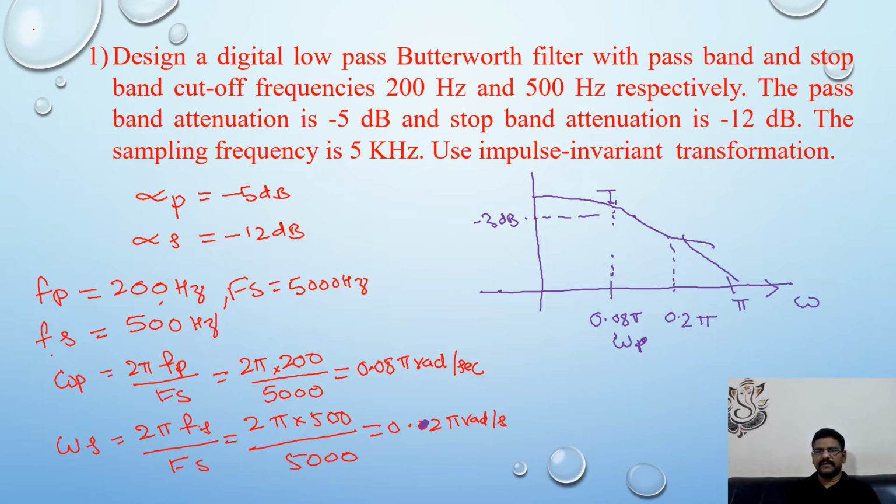So this is the required frequency response, and here we need to remember one point. Actually the maximum value is 5 and on this side minus 5. Most of the times we'll take the normalized value, meaning we'll divide the whole scale by 5. So the normalized value we can take as 0.08 radians per second, right? And this I can take as 0.2 radians per second.